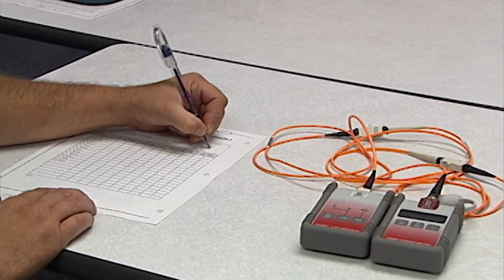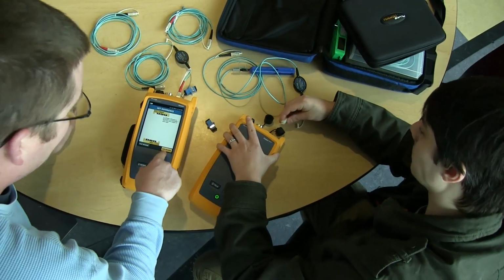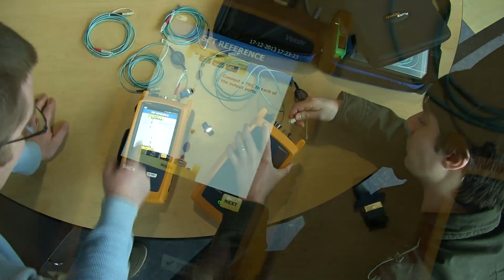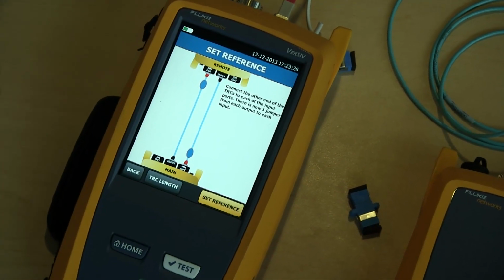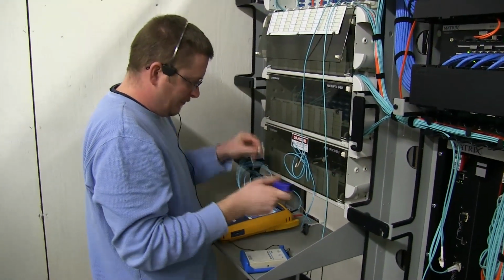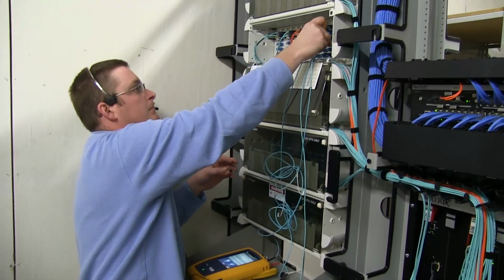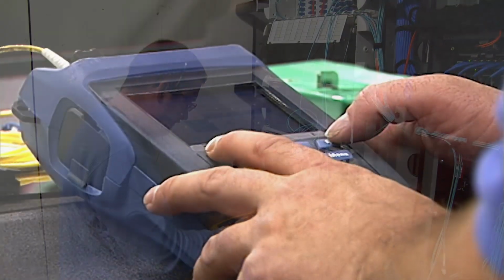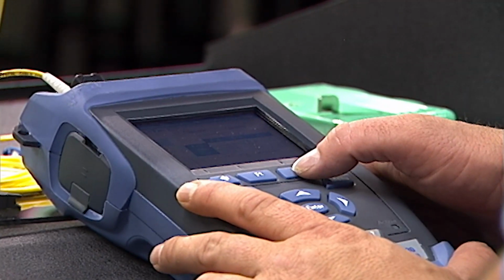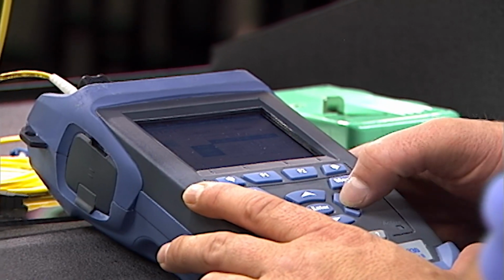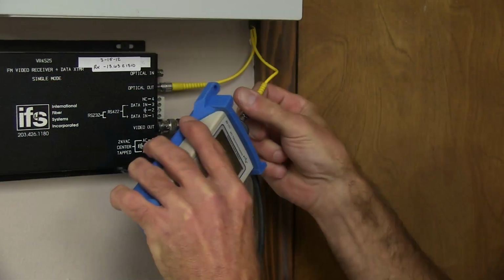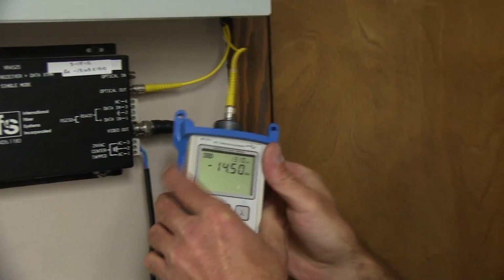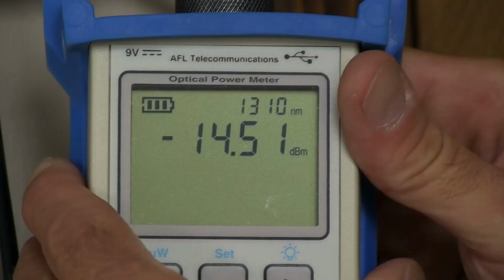The light source and power meter is used to measure attenuation by directly measuring the amount of light passing through a fiber under test and can provide very accurate attenuation readings. Optical loss testing often requires two people, one at the launch end and the other at the receive end of the fiber. The primary function of the optical loss test is to verify end-to-end attenuation of the fiber optic link, including the fiber, connectors, splices, and passive components. In addition, the power meter can be used for simple continuity checks. Light sources and power meters are the essential go-no-go instruments for fiber optics testing.